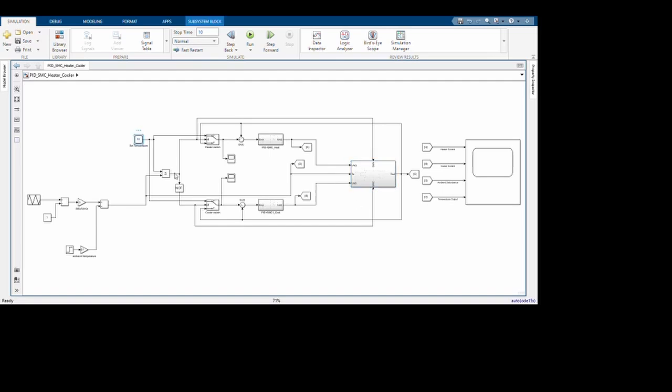This is our set temperature and this is our ambient temperature. Now, if you look, our ambient temperature is not a simple constant. We have added some disturbance. How have we done that? We've taken a 10 hertz triangle wave, and we've added it with a constant one. The reason we have done that is because we don't want any negative values. We multiply that by a disturbance gain. For now, I've kept it 3 because that's a reasonable amount.